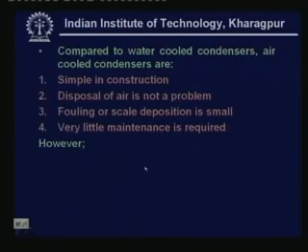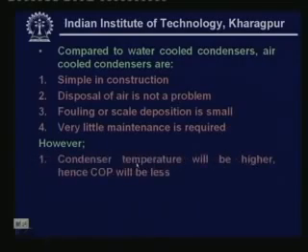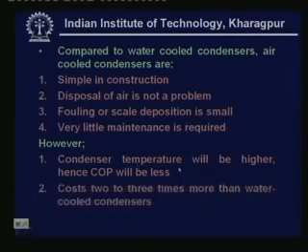However, there are certain disadvantages, as I have already discussed. Condenser temperature will be higher and COP will be less, and typically the cost of an air cooled condenser will be 2 to 3 times more than the water cooled condenser. Okay, so these are the disadvantages. That means initial cost will be high,